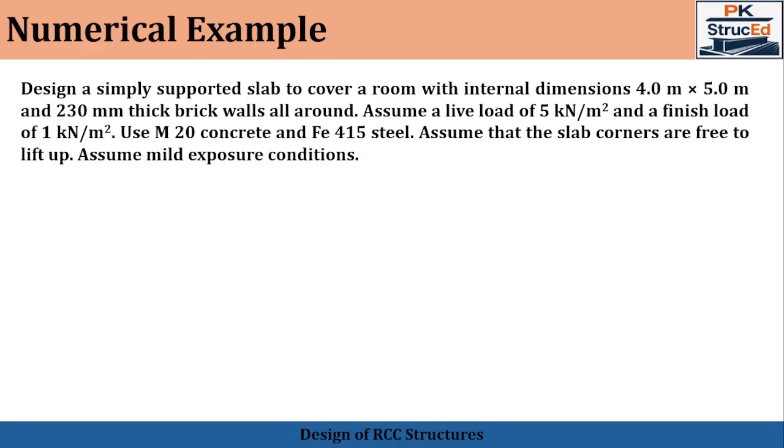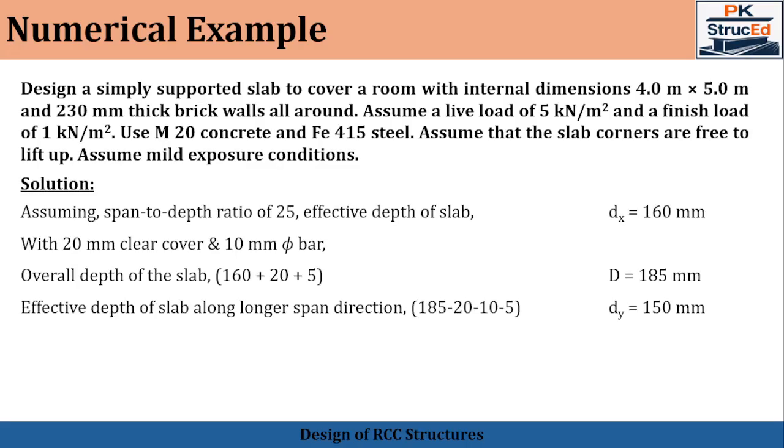As in slab design, deflection control governs the depth. We begin by assuming a suitable span to depth ratio. Assuming span to depth ratio of 25, effective depth along the shorter span direction, that is dx, can be calculated by 4000, that is the span along the shorter span direction, divided by 25, which will give the effective depth along the shorter span direction as 160 mm. That is 4000 divided by 25.